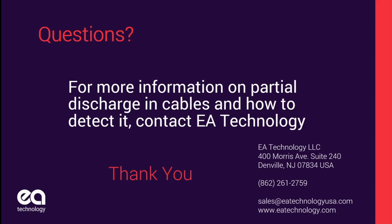You don't want to have the RFCT mounted on the ground strap and then have the ground strap fail between the RFCT and ground, because then the RFCT is going to be at line voltage. You don't want that. So you want to make sure you've got good solid grounds that are designed to handle more than the worst case ground fault current.